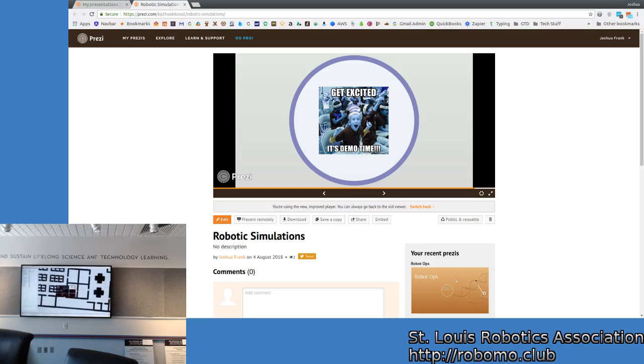Well, Josh, I don't understand something here. You said you need to tell it where the robot is. Yes. But I thought the visualization you've got was created by knowing where the robot was, right? This particular map is pre-made. It's a static map. There are different ways to get your robot to navigate. You can use static maps if you have a known office or warehouse, and that's what they're doing in this particular simulation. You can also do what's called SLAM, simultaneous localization and mapping.